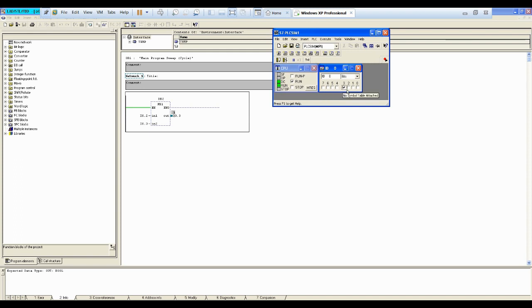So that's pretty much it about function blocks and function codes. You have clearly understood it is actually giving us an opportunity where we are utilizing our code. Like for motors we have, well, you can say at least 10 to 20 networks there depending on how big the motor is. So instead of putting all in OB1, because normally up to now we were programming in OB1, we cannot put the whole plant in OB1, right?